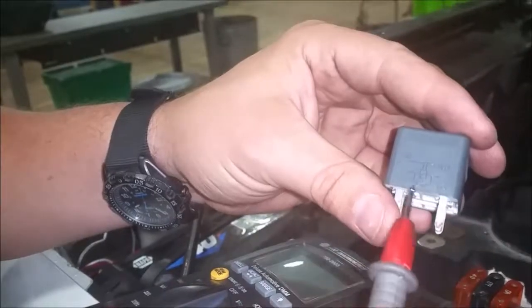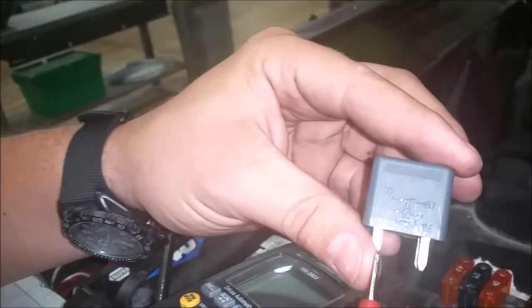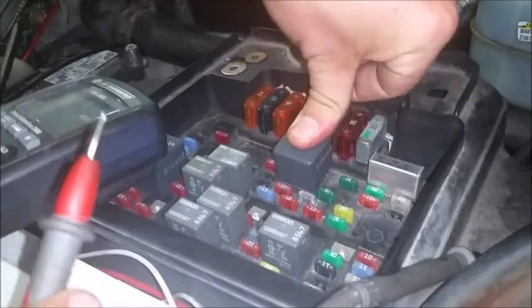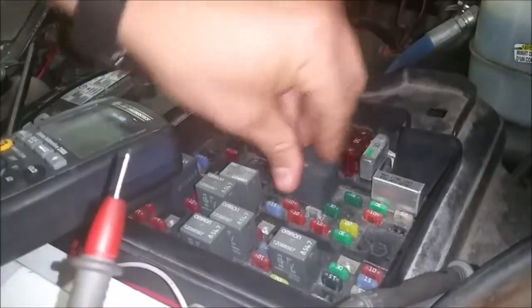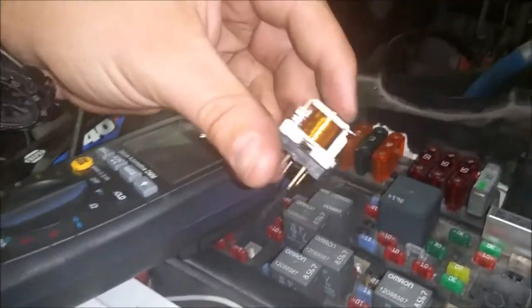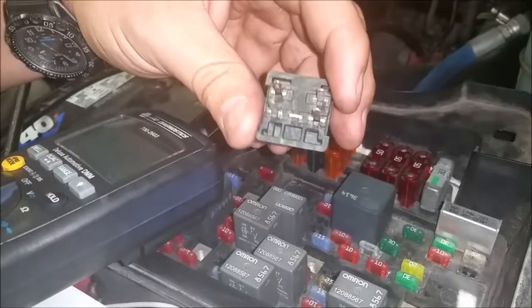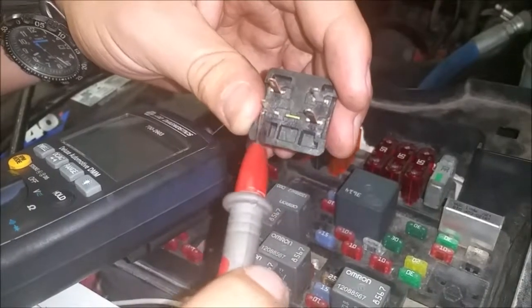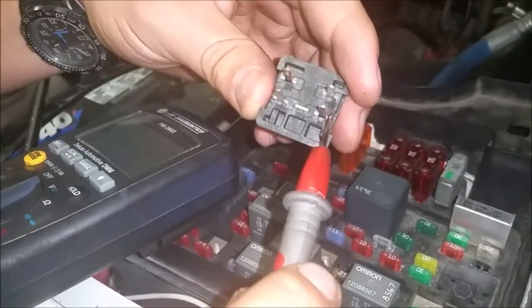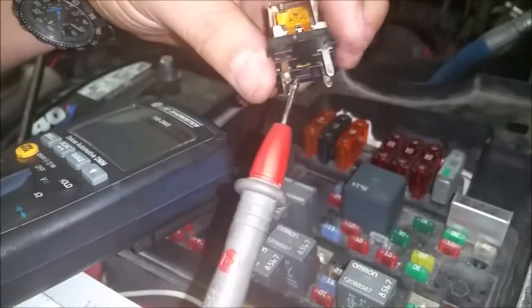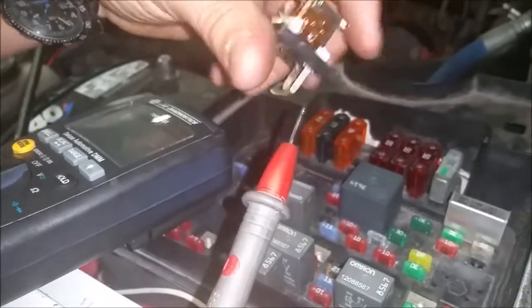If you look on most relays, it has a little diagram on the outside of it. You see that? We have a relay over here that's been taken apart. This is what's inside your electrical relay. So again, here are your pins. This one's black on the bottom instead of white, and this shows a fifth pin in the middle. But again, you've got your 30, 86, 85, and 87. So here's your coil, and here's your switch. This is what it looks like on the inside.